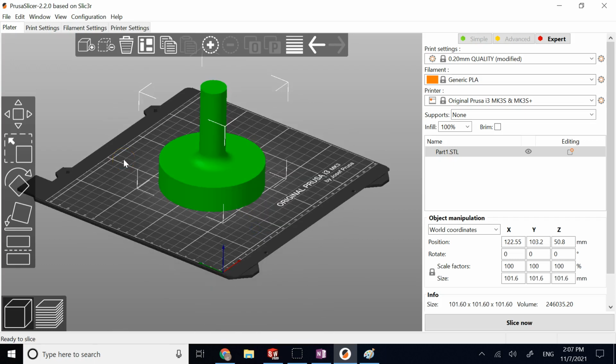But if I have this part molded, creating a part like this will be just a matter of a couple of seconds or so probably. So the plastic goes into the mold and is formed and then released by one of those springs out of the mold, and then the next one, right? So in a day, you can have thousands of this with a single injection molding machine, right? If not millions, definitely thousands of this part can be made in a day with an appropriate mold and injection machine. You definitely can do that.